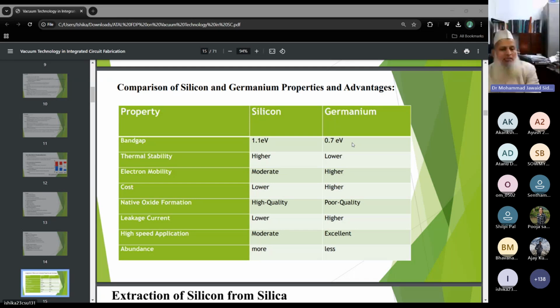You can say the device. It is very important in device applications because it can be grown directly just by heating the silicon wafer's surface in a furnace. We can grow silicon dioxide very easily, and silicon dioxide is a very good insulator. So in MOSFET, we can directly grow silicon dioxide, and MOSFET, as I told you, because of the CMOS,